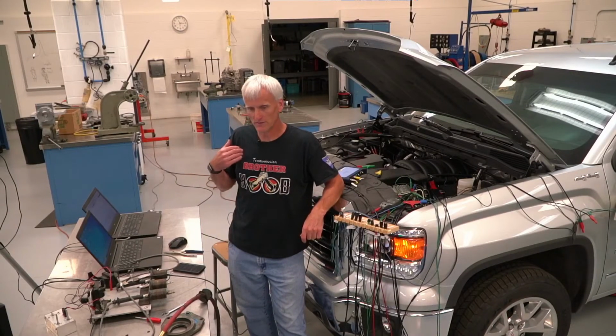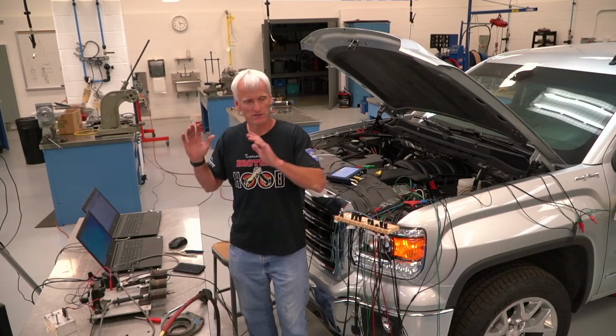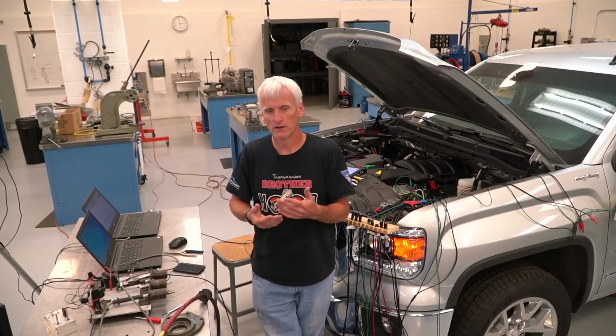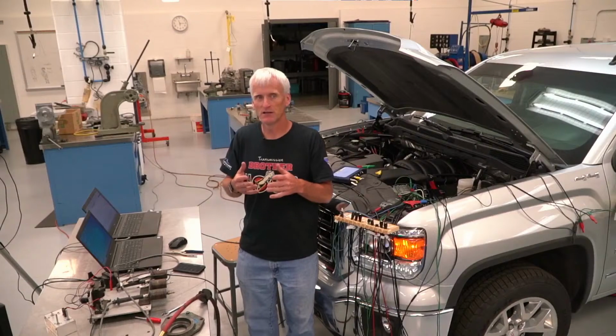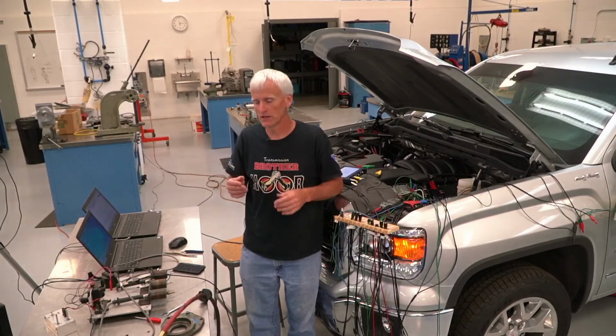And when you're doing the VE test on something like that, you can do one of two things. One is you could just not do a calculation, look to see if there's a PID on the scan tool for calculated load, and let the computer do the math for you. But I kind of recommend still using a VE calculator, because you don't want to trust what the computer's calculating. You want to look for it yourself.